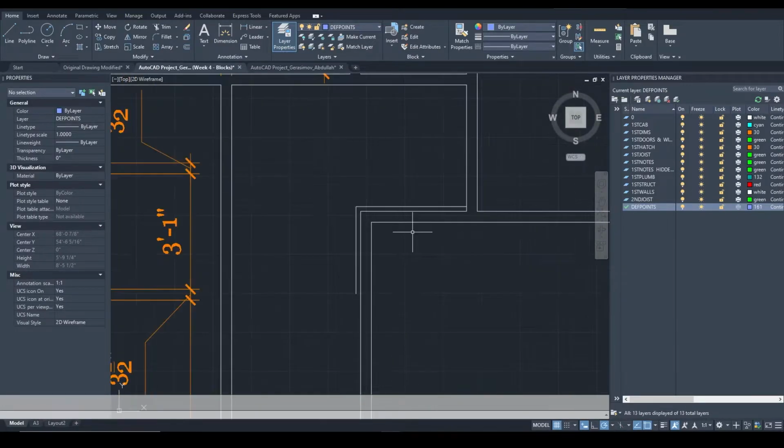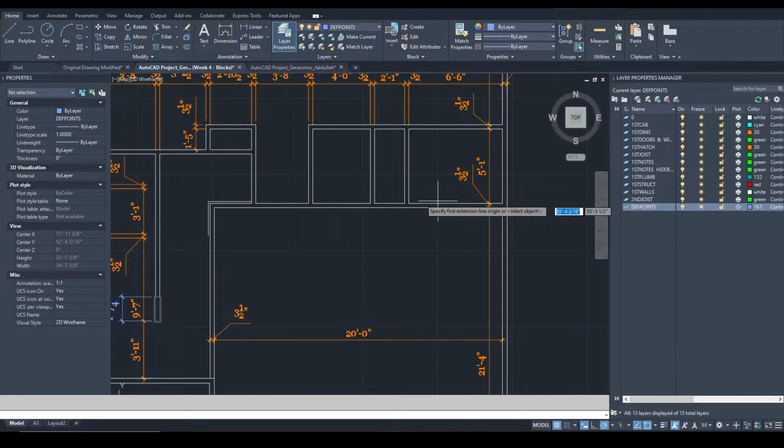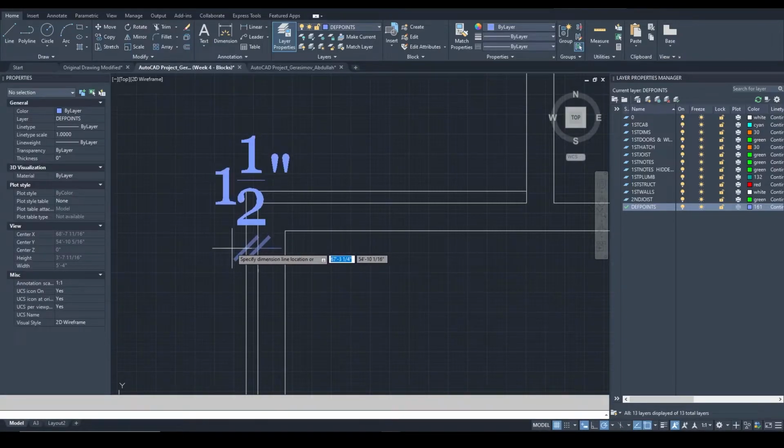Over here, you see these unfinished lines, which I will explain in more detail later on. At this point, just follow along with me. I'm not trying to get you confused, but this line is necessary for you to draw in this case. Once you draw this line and you already have this line and where it stops, which is 20 feet and 5'1" from the line that you drew at the very beginning, at this conjunction, offset this line by 1.5 inches. In the same way, offset this line by 1.5 inches.